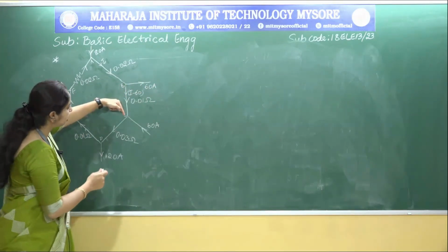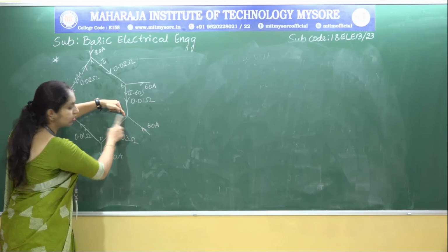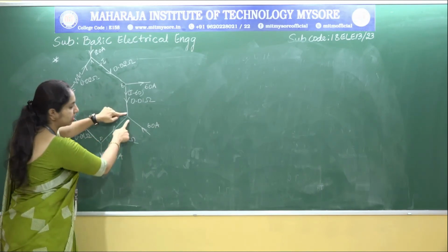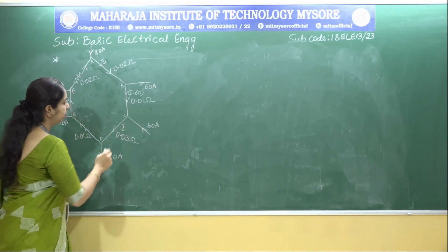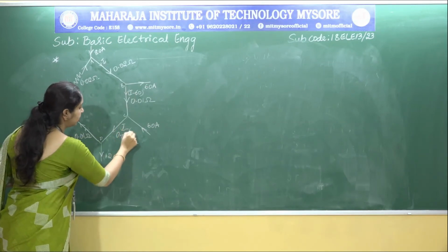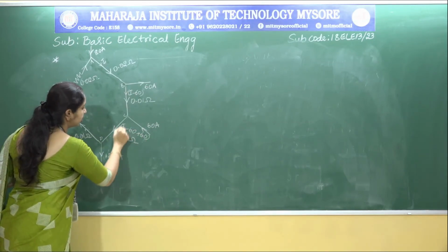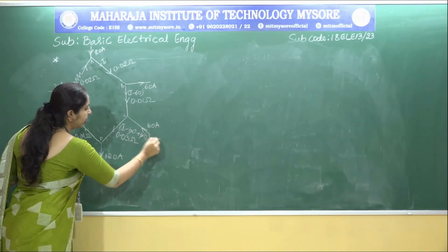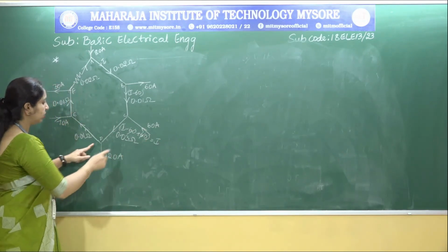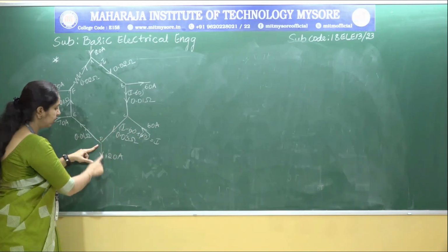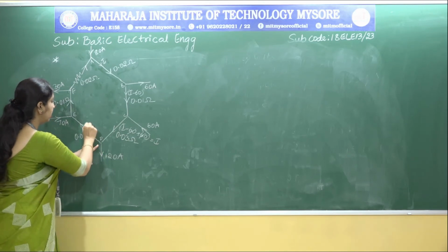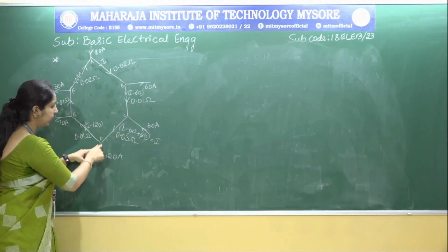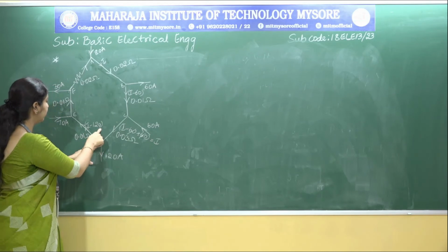Now I minus 60 is entering the junction and 60 amperes is also entering the junction. Both the currents are entering the junction, so we get I minus 60 plus 60, the 60 gets cancelled, and finally we get the total current, that is I. Now I current is entering the junction and 120 amperes is leaving the junction, so we call this current I minus 120.